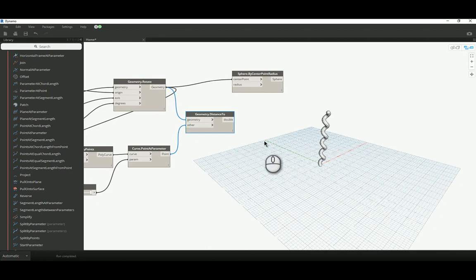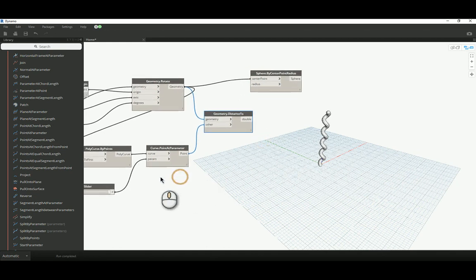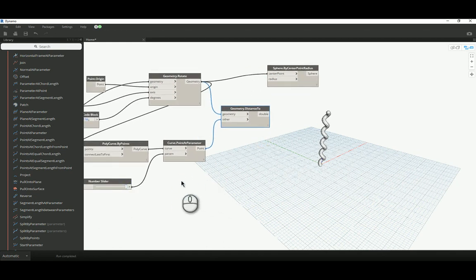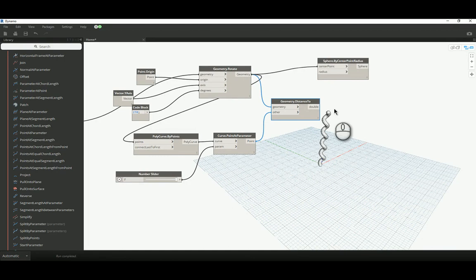The furthest distance that I have at the moment from that attractor point is going to be 30, because if this movable point is sitting at the top of this helix, the furthest distance down at the bottom is 30 meters. So that sphere at the bottom is going to be 30 meters in its radius, which is why I'm getting such a massive shape.